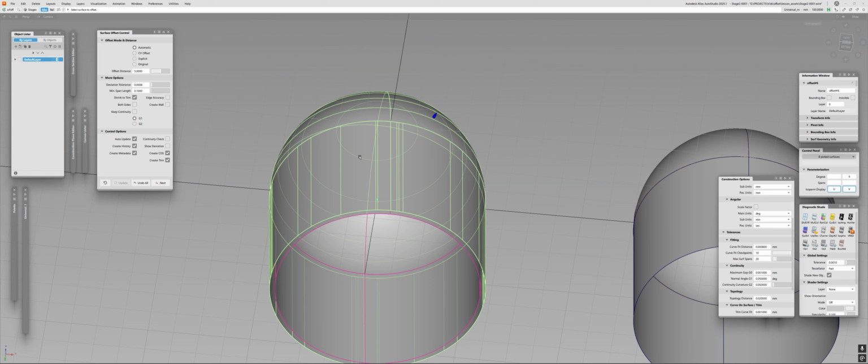Okay, now I didn't finish my sentence because I said in the beginning that you better offset inwards, not outwards. But I didn't specify why. Well, this is a good example why. When you do an offset, remember in Alias and the surface modeling tools, you create outer shells. This tool is designed to create outer shells, basically the A-type surface. There is an A side and there is a B side. A side is outwards to the user, something you can hold, something you can look at, something you can interact with.